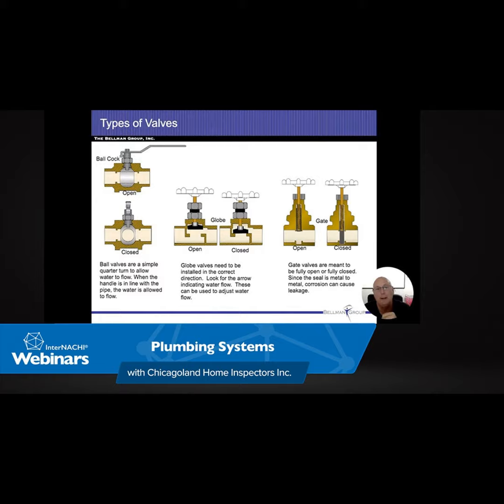I have found from experience that the hot water pipes corrode faster than the cold water pipes, which explains why the hot water lines shut down before the cold water lines do. I've also seen where the pipes go horizontal and then turn upwards, at that little elbow. They cut it off, and it was caked up, filled with debris because it kept falling right there. They replaced that section, and that gave them another 10 to 20 years out of their plumbing pipes.